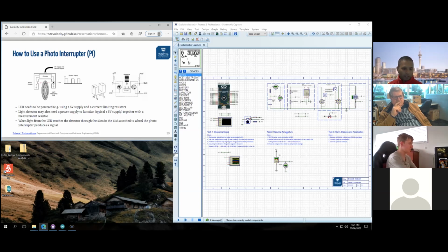The other option is we can figure out the duration of this pulse in the Arduino. If we know the duration, and we know that we are going to get 10 pulses, then this times 10 pulses, and assuming that the gap is also the same distance, times 2, would also give us how long it took to complete one complete revolution.